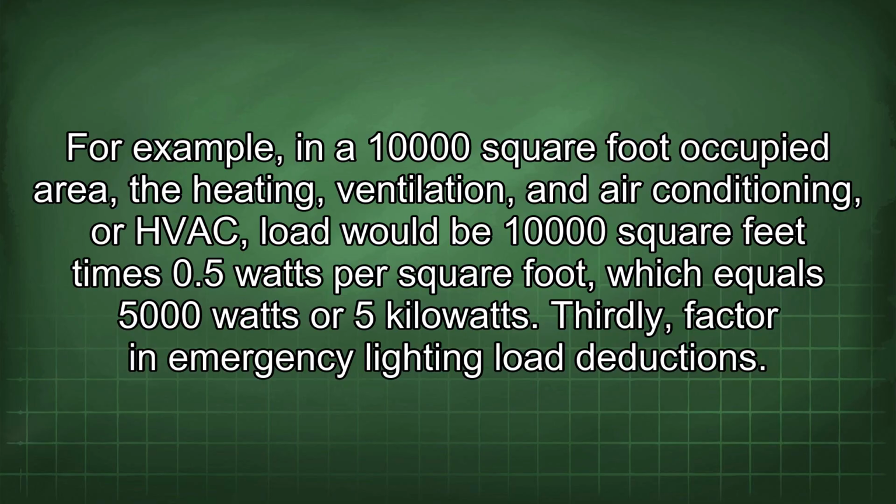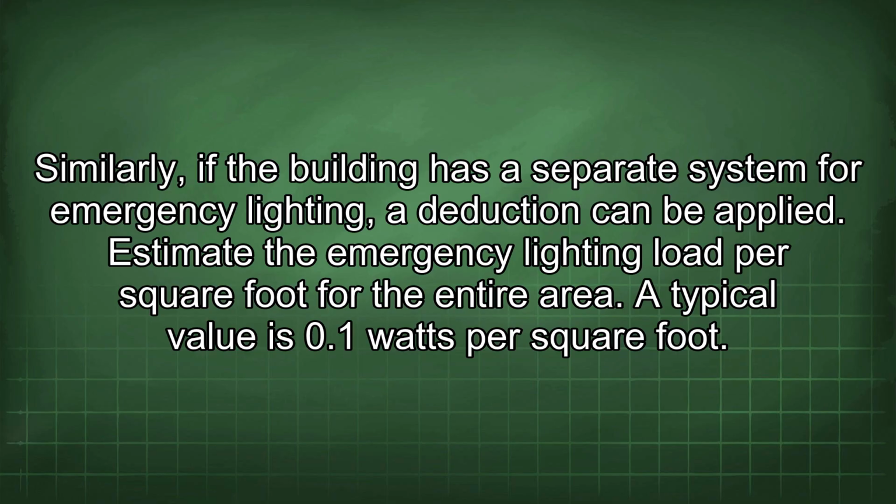Thirdly, factor in emergency lighting load deductions. Similarly, if the building has a separate system for emergency lighting, a deduction can be applied. Estimate the emergency lighting load per square foot for the entire area. A typical value is 0.1 watts per square foot.